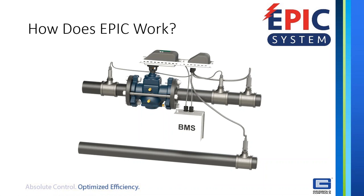So we know that if you need higher delta T, you need to slow down your flow. If your delta T is too low and you want to raise that delta T, you actually need to close the valve a little to slow down the water. And so the valve will be opened or closed based on how to dial in that delta T to get to that specific delta T requirement.